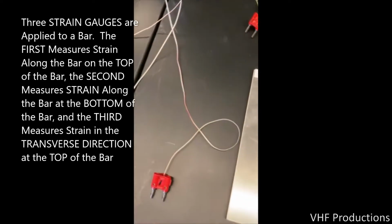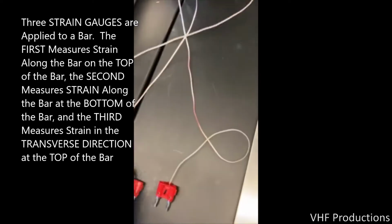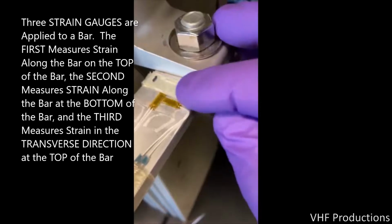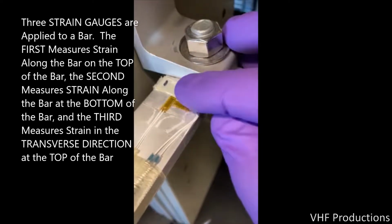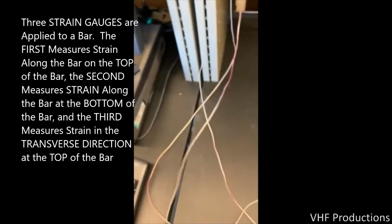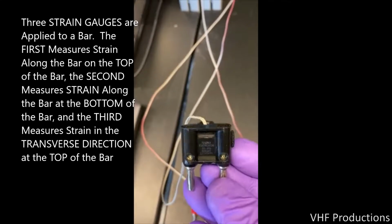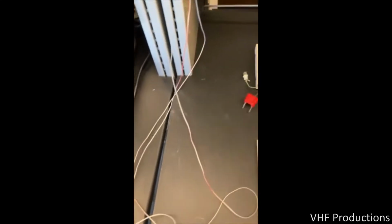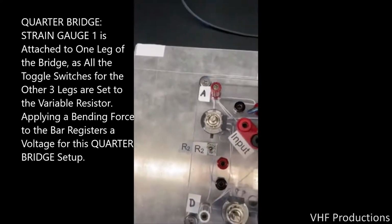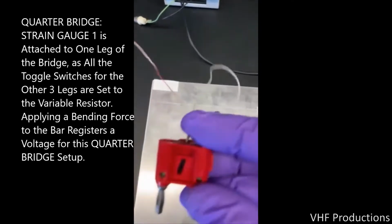This is the same configuration that we will be using for each of the 4 different cantilever beams in the experiment itself. Here we demonstrate the input from one longitudinal strain gauge aligned along the length of this beam and show how bending the beam produces an output voltage from the circuit. Each time we deflect the beam, the output, read in volts here, goes up. And each time we unload the beam, it returns to near 0.